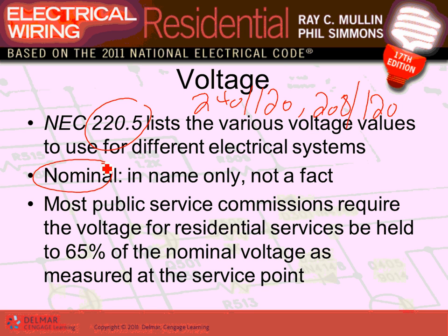Can you guys cross this number? 95. So the utilities allow you to go 5%, on equipment, plus or minus 5%. Voltage fluctuates. For example, if your system is 120, my voltage can dip 5% on my equipment and it's still doing okay. By code, you can't dip it more than 2% though, on the branch circuit. So 5% dip down or up 5%. So they can be 5% more.